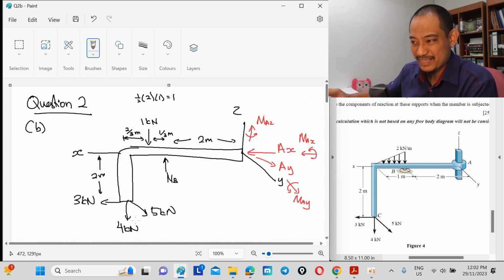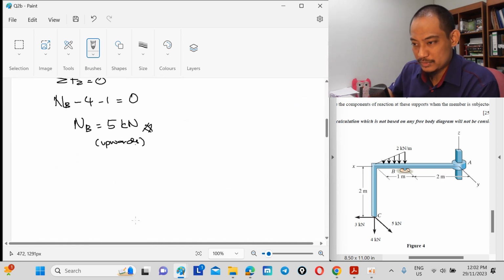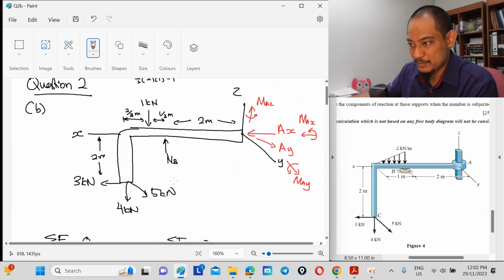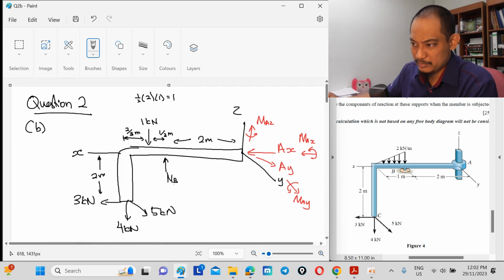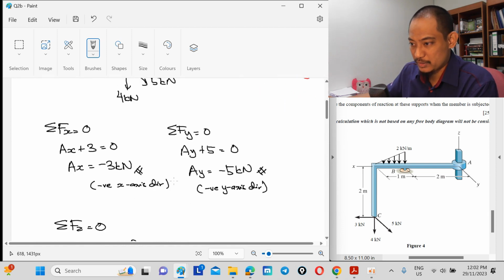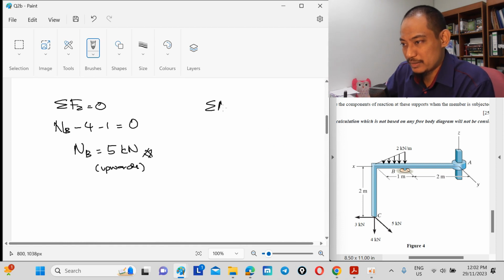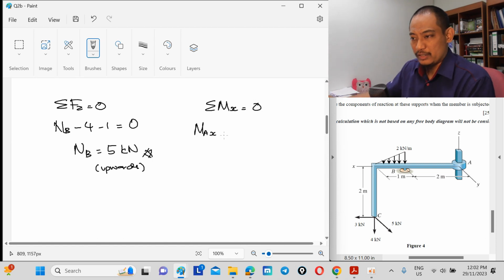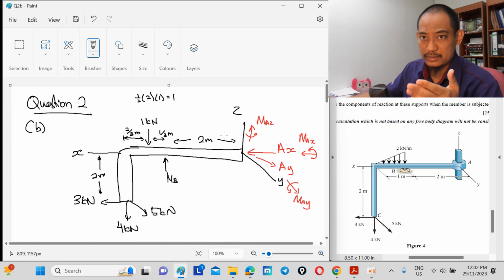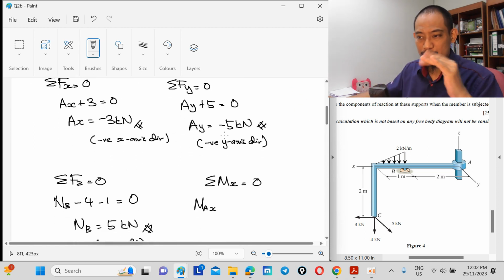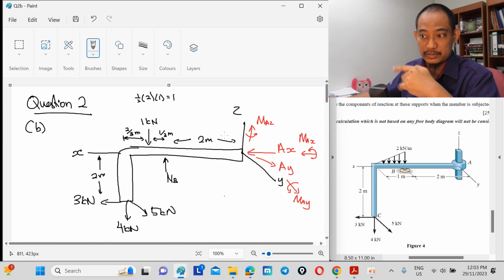And then we have MAX, MAY, MAZ, right? Because the drawing is up there, it's quite... Is there any MAX? There's none. Anyway, there's one. That's one. Okay, summation of Mx equal to 0. This is moment about x, right? So we have MAX, because now I draw everything in positive so that it's easy. So that when I calculate AX, AY, AZ it is all positive, right? But if I draw in the opposite direction, I have to calculate as negative as well. So always assume everything in positive when you have something like this.